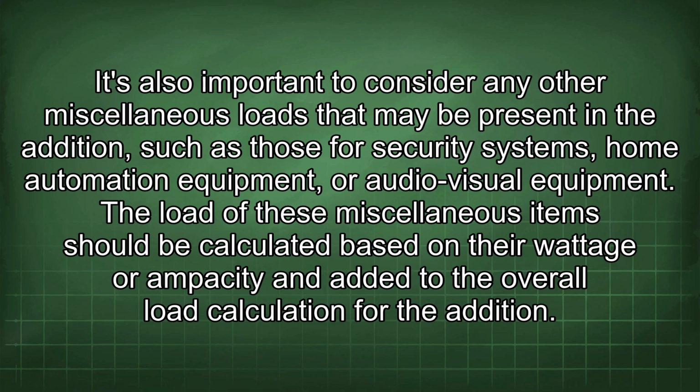It's also important to consider any other miscellaneous loads that may be present in the addition, such as those for security systems, home automation equipment, or audiovisual equipment. The load of these miscellaneous items should be calculated based on the wattage or ampacity and added to the overall load calculation for the addition.